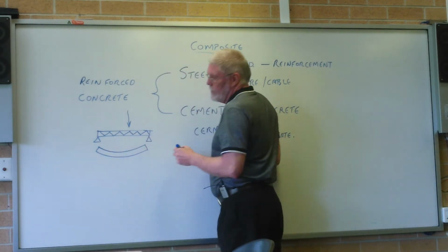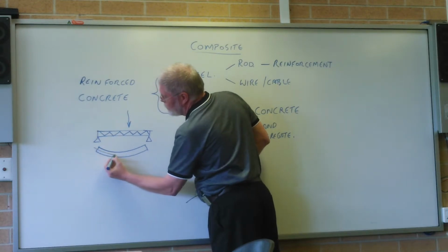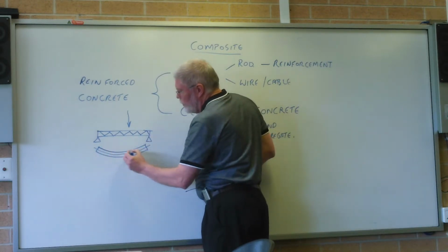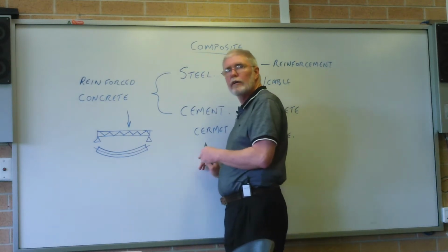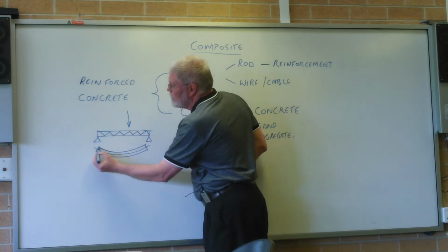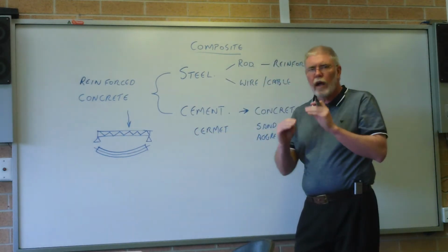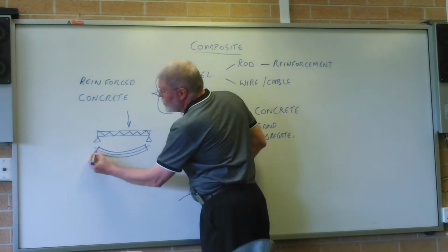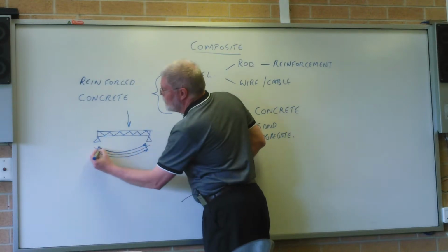But that's an effect. And what has happened, if you look at it in terms of an axis running through the middle, the top chord, that's the curved surface, or the top sector of the chord of the circle there, the arc, has shortened relative to the length of the middle part. This part here is shorter than the middle of the material, or a point in the middle of the material, a neutral axis. On the outside, it has stretched. I'll just put some arrows to indicate that. Right.